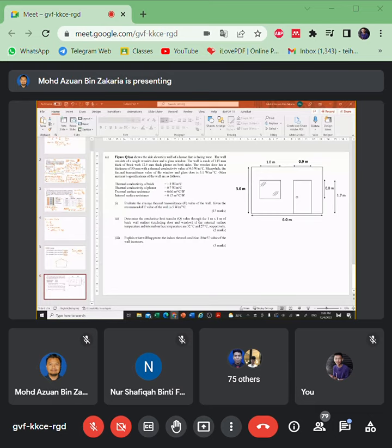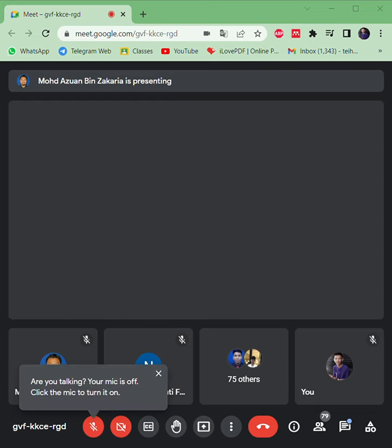R value for windows, then U value for windows. Number 4, area for wall and surface resistor. In this case, with the U value of glass and the total area, you can get the answer. Because I didn't inform about surface temperature, normally in actual conditions we need to consider surface resistance. But in this example, please ignore surface resistor to simplify things. Please calculate here.